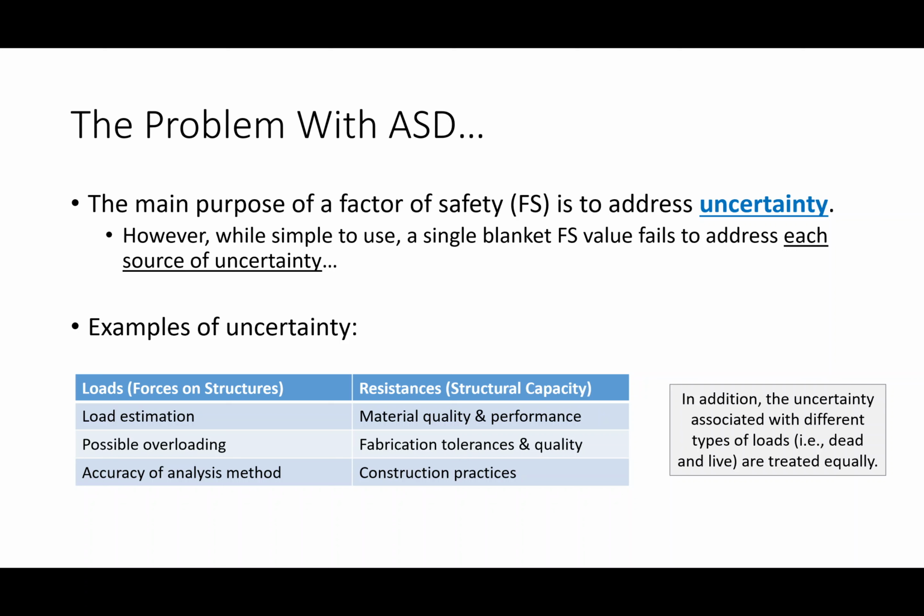And we can actually categorize those in structural engineering pretty well. So for example, on the resistance side, we can quantify uncertainties with material quality. We can quantify uncertainties with construction practices and whatnot if we do the research and monitor that. Same thing with loads. I mean, for example, take snow loads. We've been collecting snow data for years, right? So we can tell you what the snow load is in Huntington, West Virginia, and give you some confidence interval as to whether or not that's right, okay?